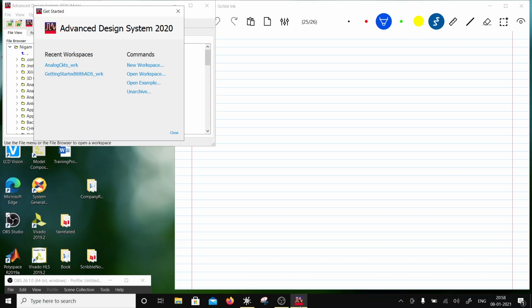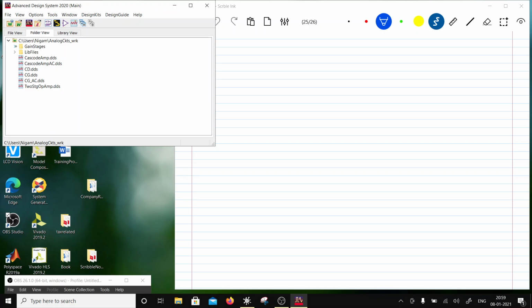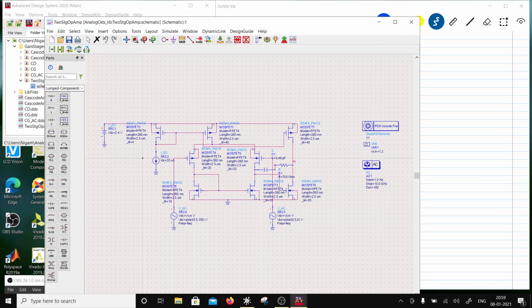This is Anurag Nikam, and last time I had discussed a two-stage amplifier and its high frequency response. This was a circuit of a two-stage op-amp. First is a differential stage, and then the second one is the common source stage. What I was saying was that this two-stage amplifier cannot drive a resistive load. So whenever you deal with resistive feedback and all that, you cannot use this two-stage amplifier as is, right?